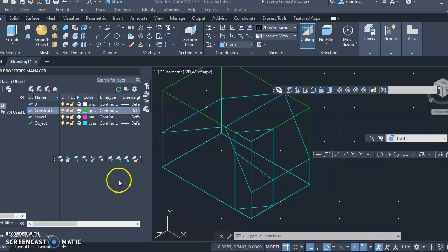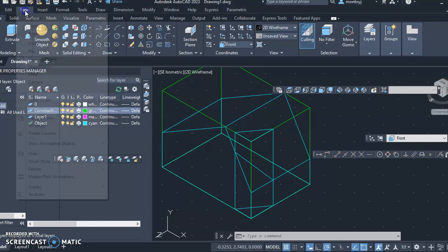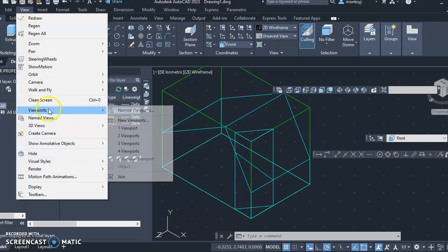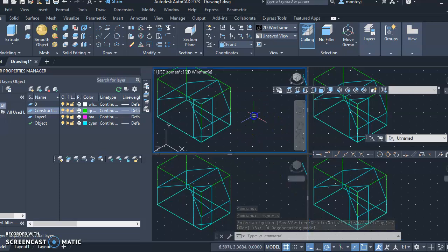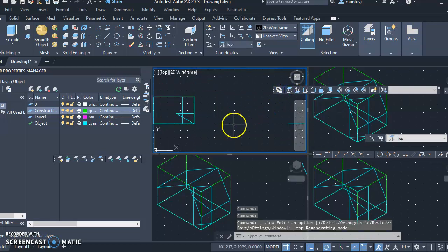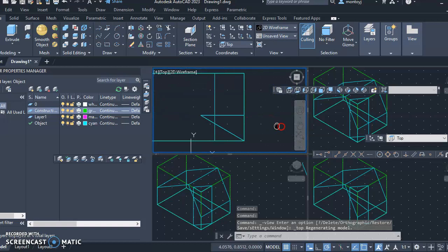Okay, I was just about to delete and go on with my life, but suddenly I turn the page and the book is going in another direction. It wants you to go to View, Viewports, go to 4 viewports, and voila, you have 4 different views. When you highlight one and it creates the blue frame, we're going to create an easy orthographic, and we'll set this to top view and bring it into view.